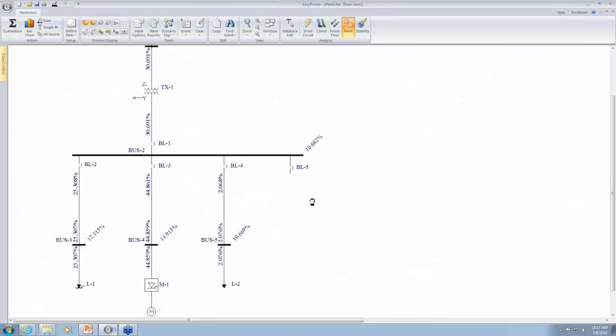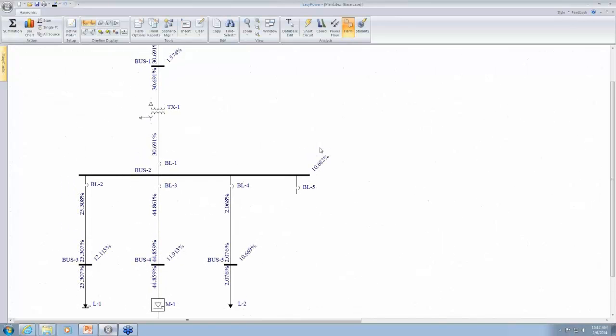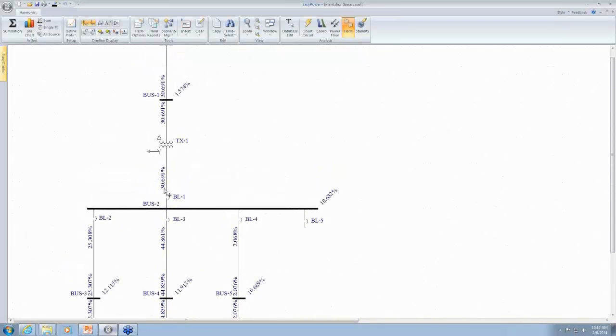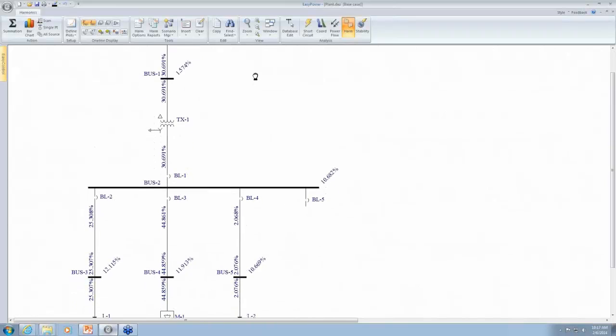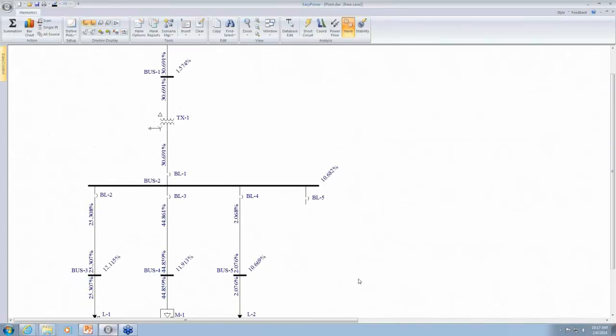We can see that the harmonic distortion on the voltage is 10.6% and on the current is 30%. In typical practice, we would like to limit the voltage distortion to something like 5% or less.